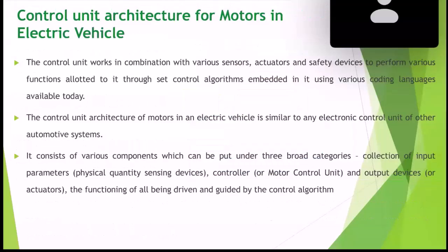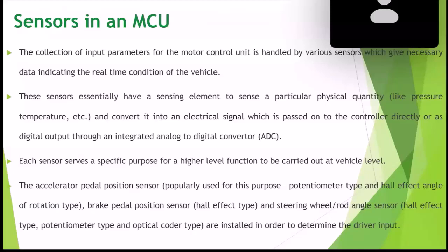The control unit works in combination with various sensors, actuators, and safety devices to perform the various functions allotted to the set of control algorithms. Basically, it is a microcontroller-based control system used to control the motor. It has a variety of sensors, starting from vehicle speed and driver requirement, for example accelerator pedal position.